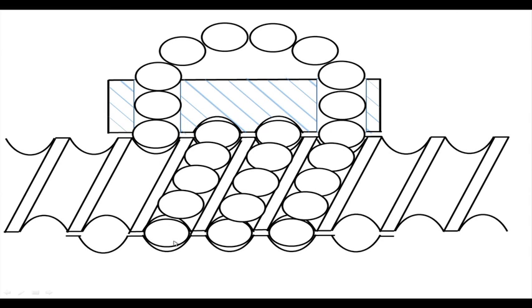On the other side, they move up, roll in between, come out, and again get recirculated like this. So, sliding friction is replaced by rolling friction, and if these balls are a little oversized and with preloading, one such nut preloaded against another nut with some actual loading, in that case backlash can be eliminated to a large extent.